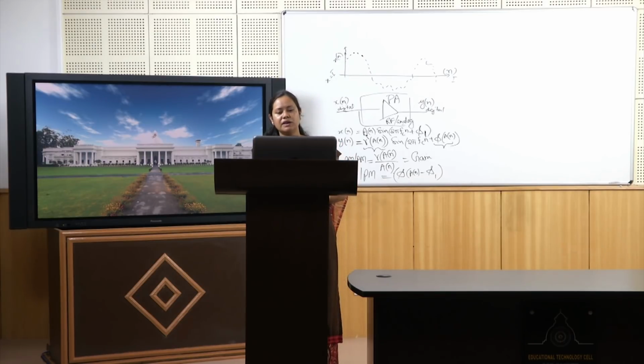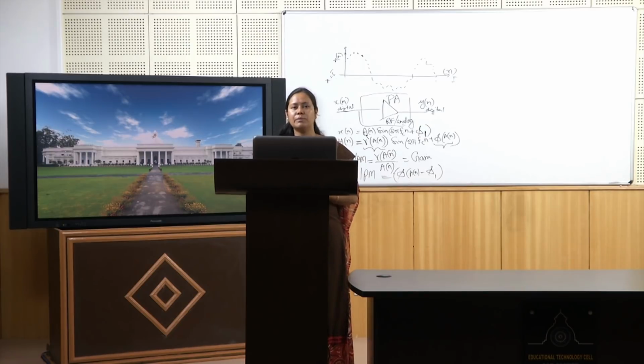Another thing we come across in the power amplifier is the memory effect. Memory effect comes into the picture because of the heating of the devices. Moreover, the energy storing components in the power amplifier, like inductors and capacitors, sometimes to block the DC we have to use a capacitor. These elements store the energy and then release it according to their nature, according to their time constant.